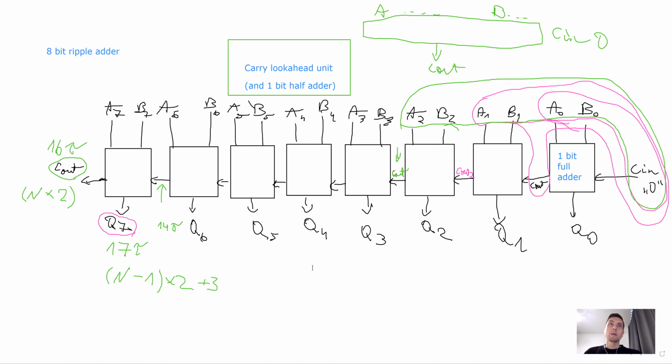Okay, so I guess that's all for today. This is how I tried to explain how we build 8-bit adders. The number of adders is equal to the bit number of the architecture. 8-bit processors have 8-bit adders, 64-bit processors have 64-bit adders, and they're basically built from 1-bit adders, which are built from logic gates, which are built from transistors. So actually pretty simple stuff.